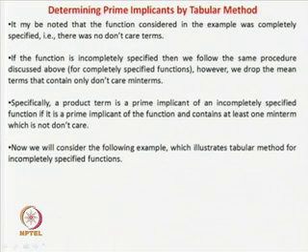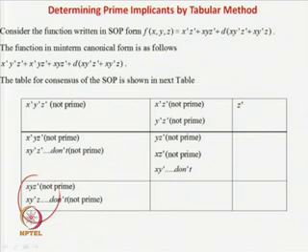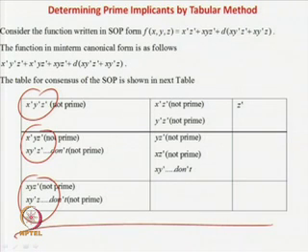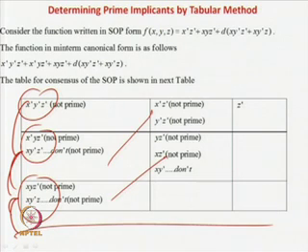But if you observe, this was our basic idea, if you remember. So, we had a table like this. This one is having only 1 prime, this one is having 2 primes, this is having 3 primes, there can also be a row having no primes. Then we have consensus in between these 2, and then between these 2 in terms of this set, and then finally we generate the next set of terms, and then again we have consensus between these 2, and finally we generate this one. So, this was the procedure we have already seen.